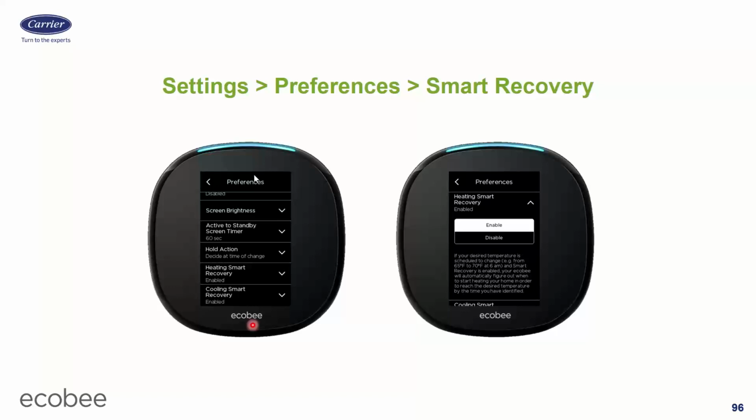With Ecobee, it does everything like I just said, plus it keeps a profile of your home. So it doesn't just look at the past day or past 3 days. It knows a profile of your house. It knows how long it takes to heat and cool your house on a 17-degree day and a 25-degree day and a 41-degree day. It knows how long it's going to take based on the history it's been collecting on your house. Everything that the stat knows goes up to the Ecobee server, up to the Ecobee cloud, and gets stored there on your house. So it knows your house and how long it takes to heat and cool your house, which makes it predict this a little bit better.